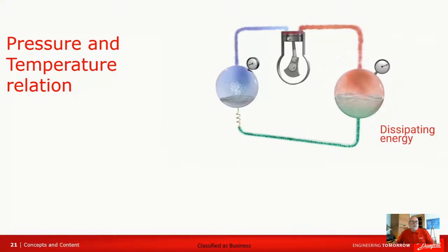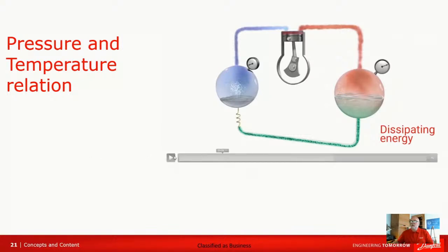There's a question, how to know if the compressor is turning the right way? That's a good one, actually. And the simple answer is, it depends on what type of compressor it is. What you have here, the one that we're showing here, is a reciprocating compressor. And you might be able to tell that even if the motor is turning the other way around, the piston is actually doing the same thing.